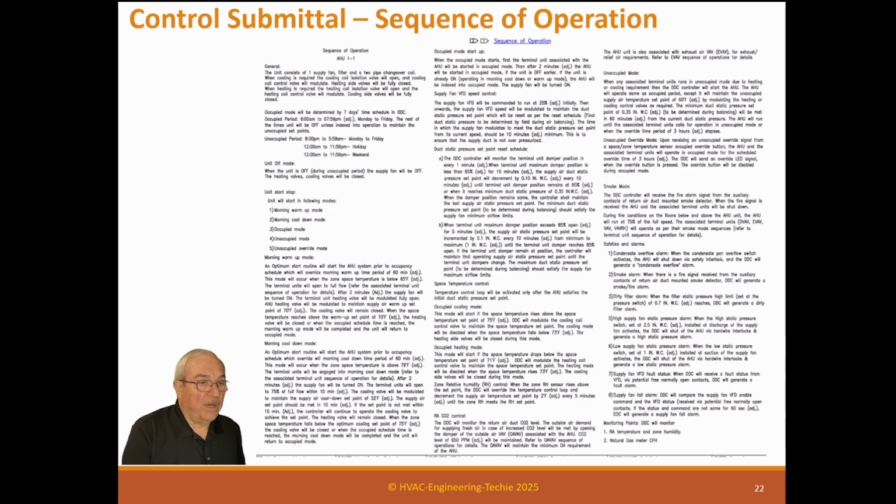Well, the way it's supposed to be is the engineer puts on the drawing or the spec his sequence. The control contractor takes it and modifies those sequences to include all his special syntaxes that will provide the sequence the engineer wants. And that's what he's supposed to do. Well, 99% of the time, the control contractor simply photocopies the engineer's spec and pastes it in his submittal. And the reason they do that is so they won't get disapproved. It's fine, except it don't work.